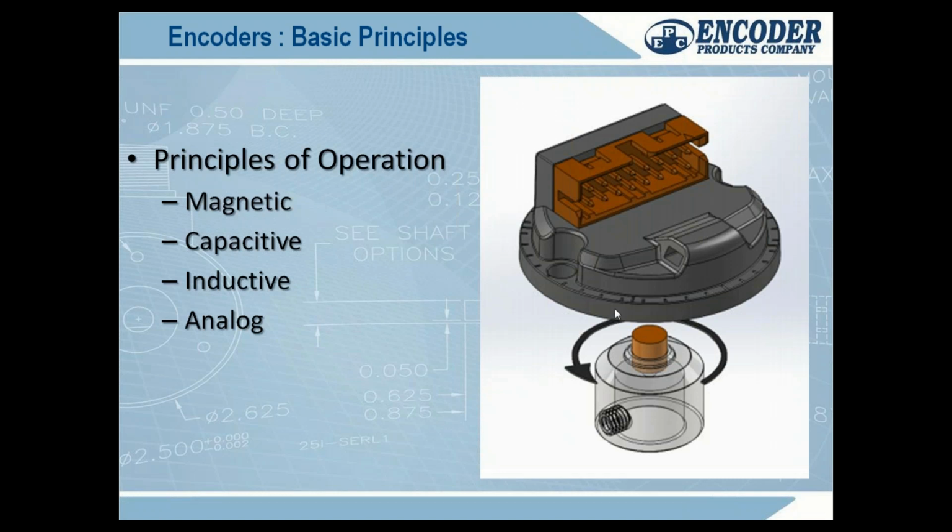This is a picture of a magnetic encoder. It has a small neodymium magnet here. It's two-pole. If you were to draw a line here in the center, you have a north side and a south side, and it's up inside of this. There are some fancy Hall effect sensors that detect the change in the magnetic field, and rinse, repeat. At the end of the day, it takes a sinusoidal waveform created by that spinning magnet, it squares it, and it makes square waves.